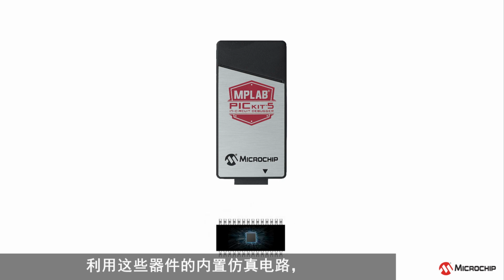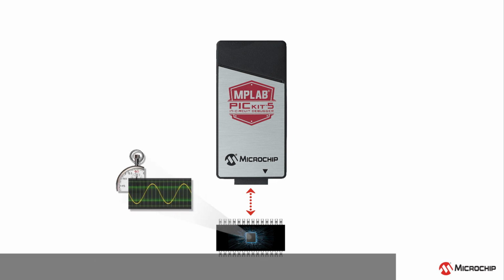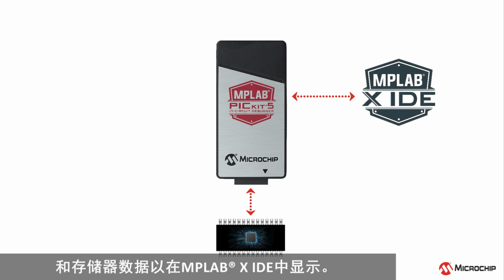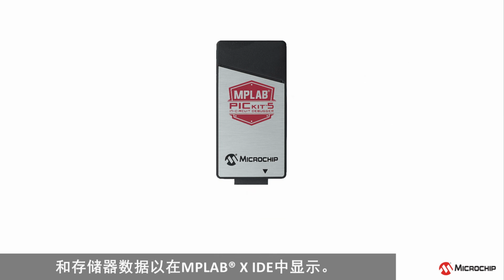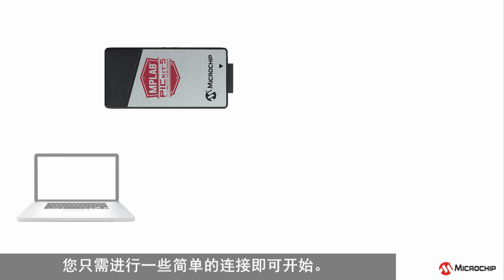Utilising the built-in emulation circuitry of these devices, the PICkit 5 can execute code with true electrical and timing characteristics, conditionally halt execution, and upload program flow and memory data for display in the MPLAB X IDE. You only need make a few simple connections to get underway.